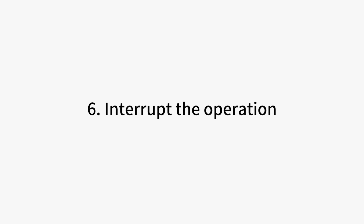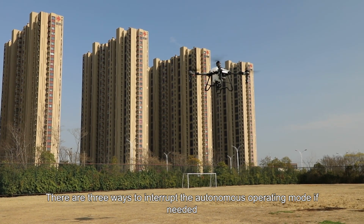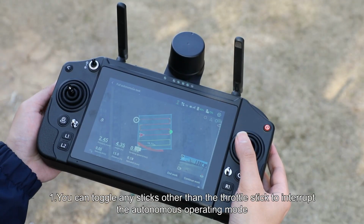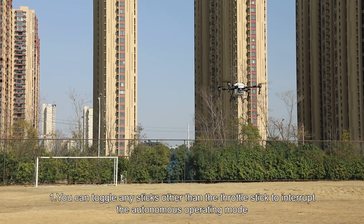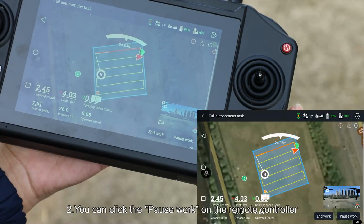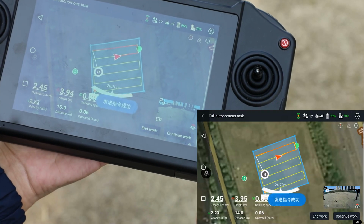6. Interrupt the operation. There are 3 ways to interrupt the autonomous operating mode if needed. 1. You can toggle any sticks other than the throttle stick to interrupt the autonomous operating mode. 2. You can click the pause work on the remote controller.